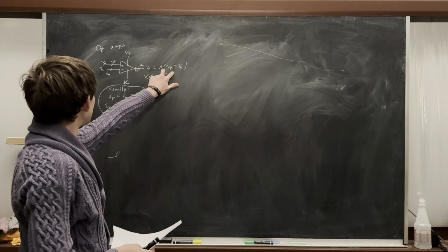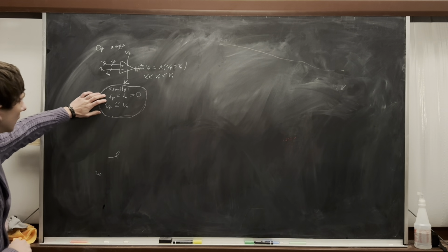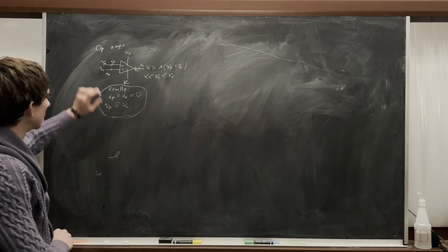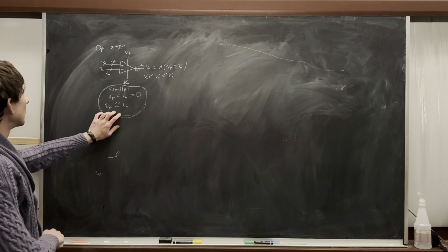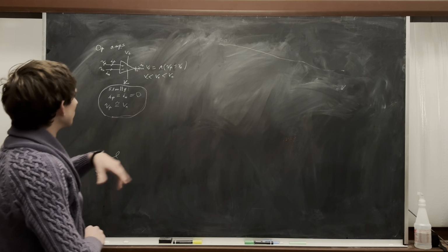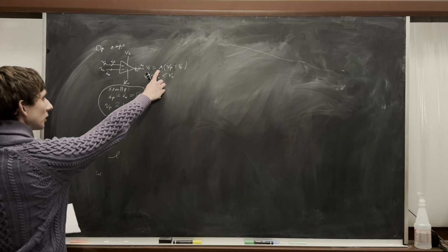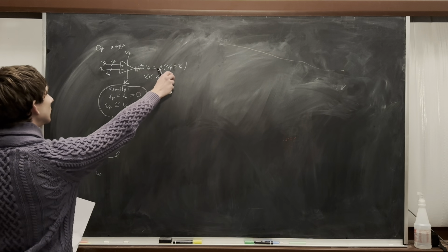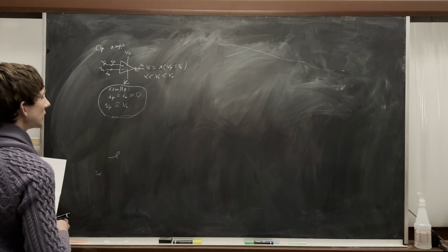We don't generally use this that much because we end up assuming these things for an ideal op amp. IP equals IN equals 0, so no current entering these, and VP is about equal to VN. We generally treat them as being equal. Of course, if they really were equal, V out would always be 0, but A is on the order of tens of thousands, so if they're really close to each other, then this difference times A will end up being something somewhat finite.